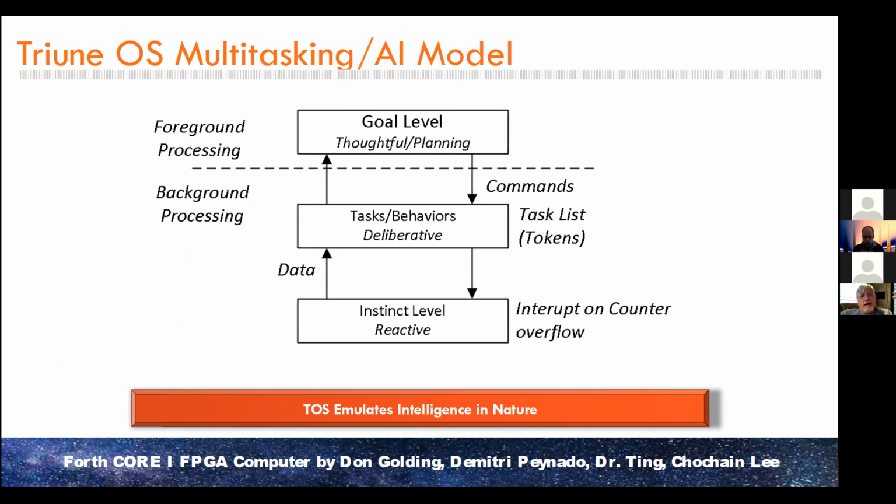The multitasker is kind of interesting in this system. What I did was I used a counter timer, and I do a periodic interrupt. This is how I built this. And it executes, say, 1,000 times a second. In the interrupt service routine for that counter timer interrupt, the first thing it does is read all the sensors in the robot and update variables in the memory space to the new values of the sensors.